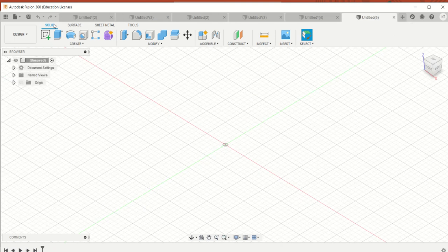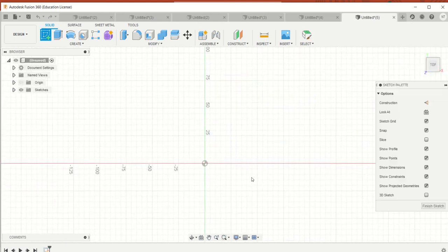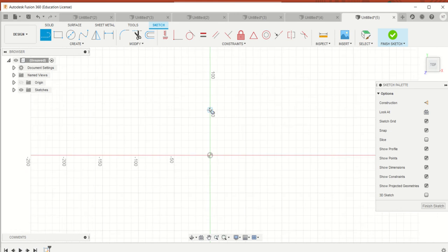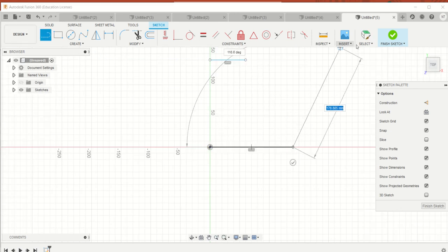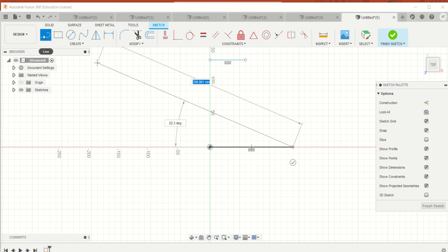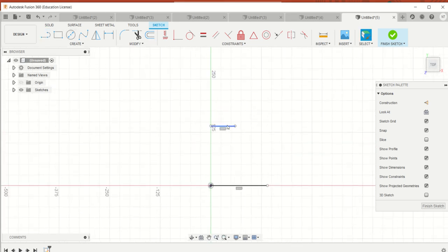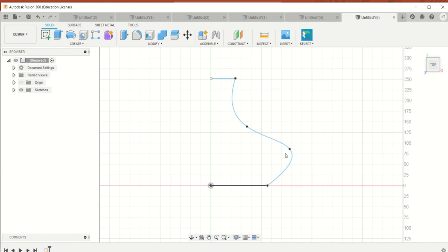Let's try another very simple vase. So we'll choose a top. We'll choose a bottom length. This might be just a little too far, so let's just move this up here. It's already constrained to the horizontal, so I can't change it. So I'll put it over here. And now I'll go to spline. Make a couple of inflection points. I'll finish the sketch.